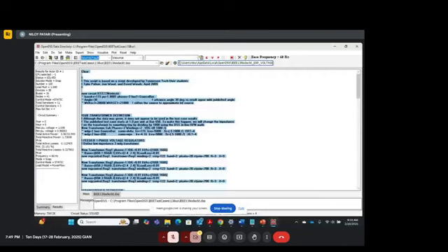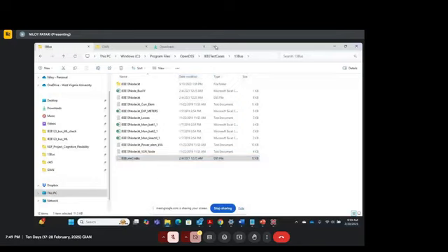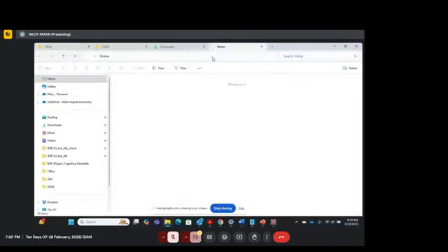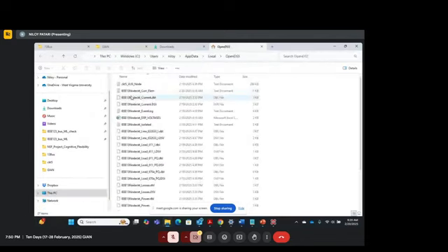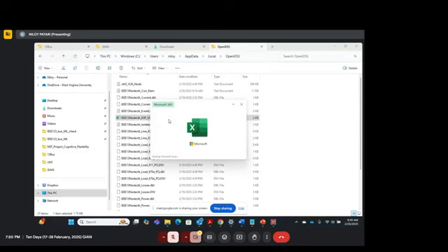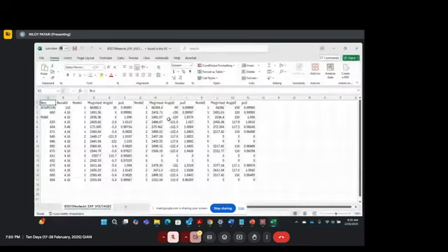If you export that voltage, it will be exported to this particular location, which you can define on your own. But here, if I go to this particular folder, yeah, this is the one. So you can export voltages, currents, powers in CSV file. Once you export this file, you see that it shows magnitude, angle, per unit values, and everything.